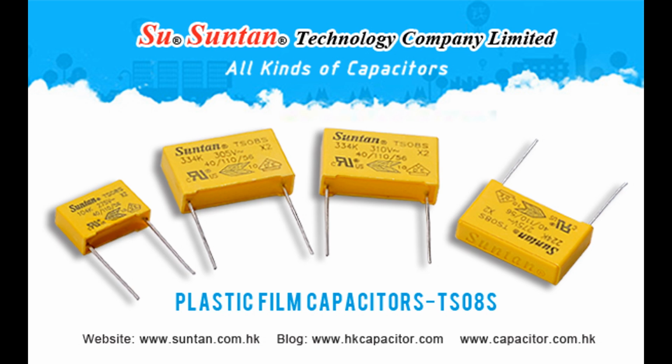Frequency stability. The capacitance of film capacitors remains stable at different frequencies, making them ideal for high-frequency applications like oscillators and RF circuits. 2. Low dielectric loss. Film capacitors have extremely low dielectric loss or dissipation factor, DF, which means very little energy is lost as heat during operation. This is particularly advantageous in high-frequency and high-power applications where energy efficiency is critical.